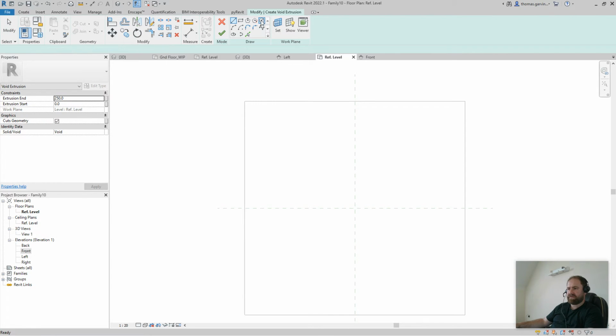Okay. Circle. Doesn't matter, just bang it in there somewhere like that. Escape, escape. Select that guy and tick the center mark visible. Okay. Escape, escape. You see it now? We have a center mark that we can align and lock to, okay, or dimension from. So using your align and lock tool, align to the reference plane, make sure lock is selected. Bing, this one, boom, escape, okay.